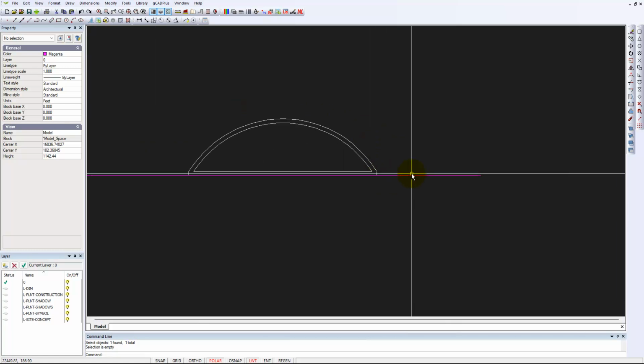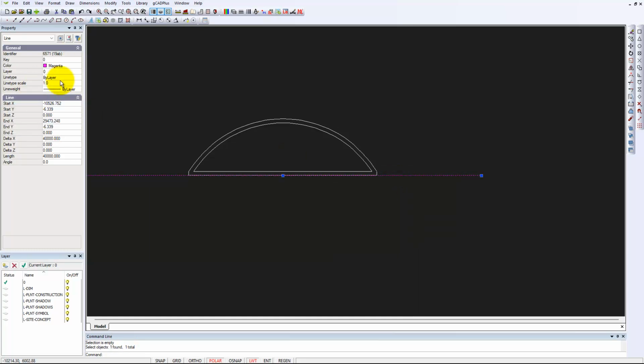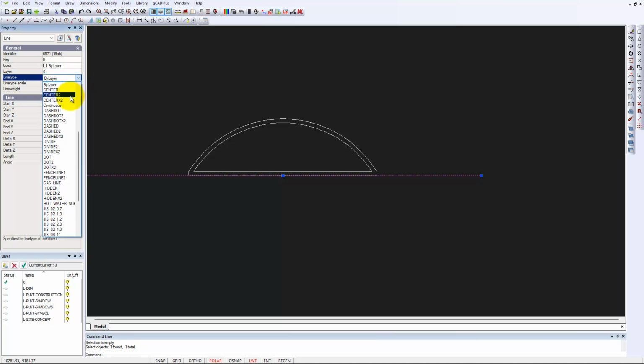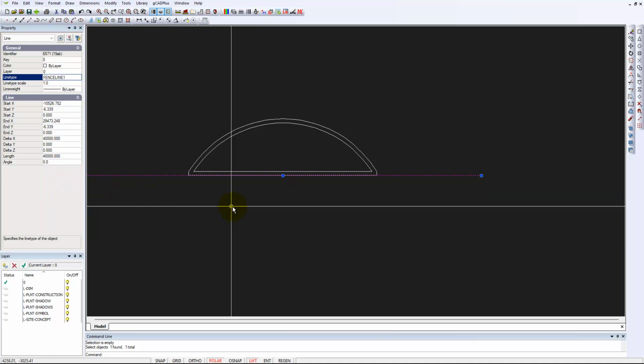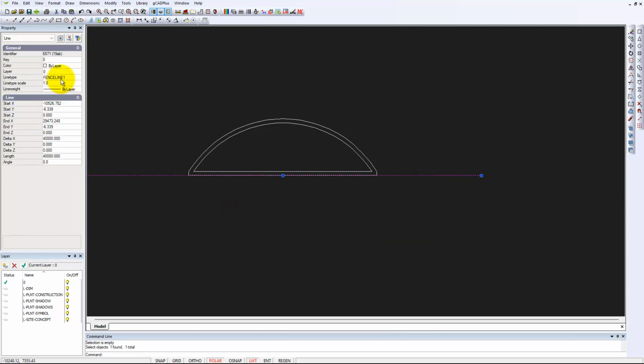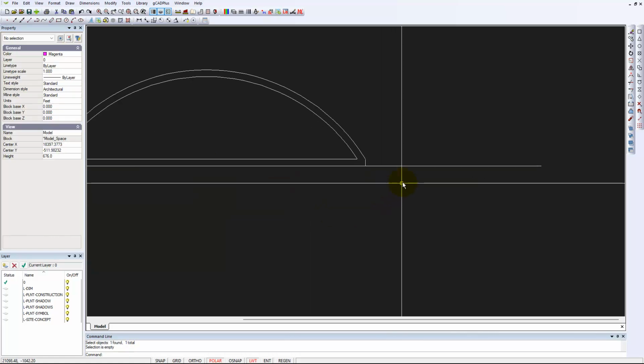In this case, we might want to give that line some properties. I'll change back from drawing color magenta, and we'll set a line type. We have a couple of fence line options, and I'll set that, and we're done. So when I select that line now, it's got special properties of a fence line, but we don't see them yet. We have to adjust the line type scale, and I'll guess around about 25. And I'll change that scale. Still doesn't show.